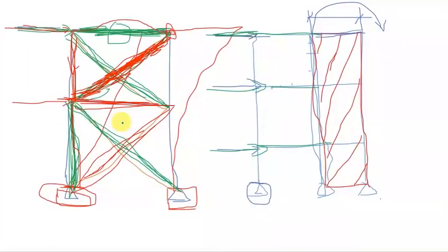So you should be good in designing these bracings, because maybe in one of your projects you'll meet one which requires that you design the bracings. Even if you do a water tank, you have to provide bracings. If you can't do moment connection, I'm sure you've seen a water tank or an electricity transmission tower. You've seen a tower having so many bracings. Those are meant to transfer just the lateral load. Okay, and it should not intimidate you in any way.